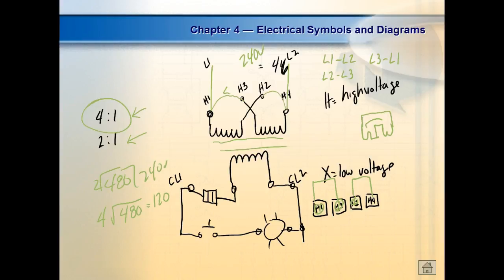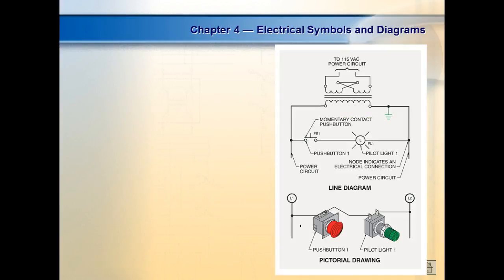As soon as I get over to the right one. So this one right here is wired for high voltage. So they're putting 115 volts up there. If that's divided by 4, what would we be getting on the secondary? What would we be getting? 28.75. Yeah, so probably up at 24 volt control.